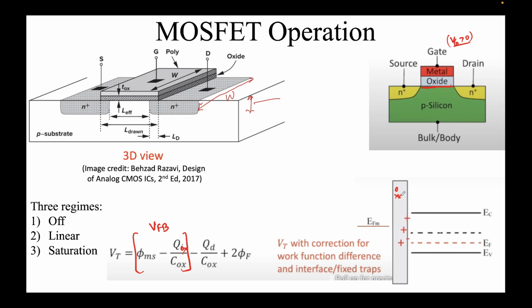So this was the oxide layer, this is your semiconductor, and this is your metal. From MOSCAP we had seen that, and the other 2 terms, this was coming from the band bending or the strong inversion, and this term was the depletion charge, because inversion will happen only after the depletion.